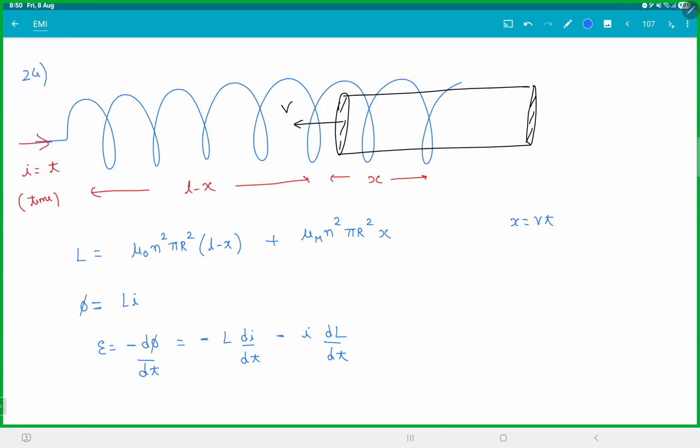Because whenever you ask someone about a solenoid, there's L dI by dt. L dI by dt. It's like asking F is equal to ma, which is a blunder. If m is constant, then F is ma. If L is constant, then it is L dI by dt. Here, L itself is changing. Clear with this? It is easy to solve, but you should realize, boss, L is changing. I can't use L dI by dt. There's nothing big deal about the question other than that. Clear?